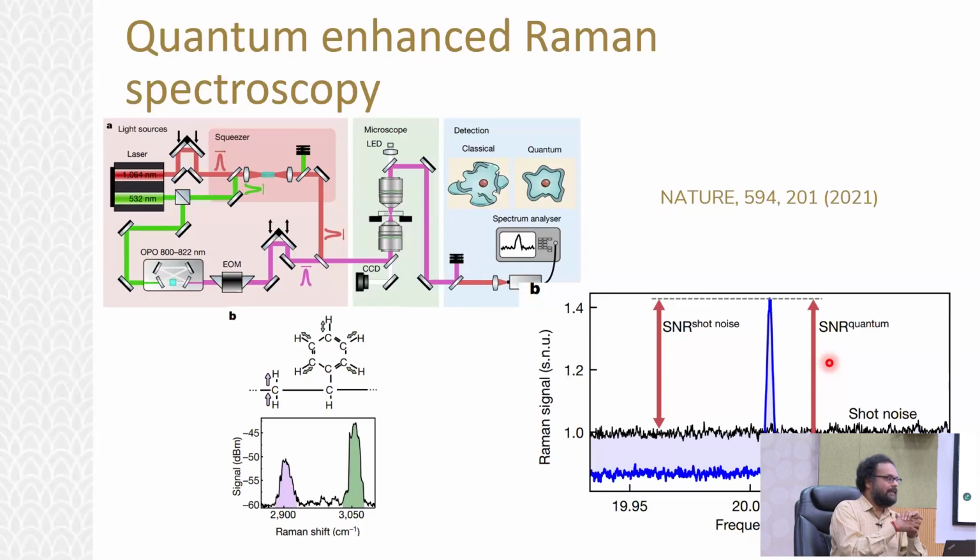They do the homodyning as well, like what Wu proposed, and that gives you access to very important parameters. And what they have done, measuring from a signal analyzer, is they are able to reduce the noise floor of the measurement. This is the shot noise limit, and they can go beyond the shot noise.